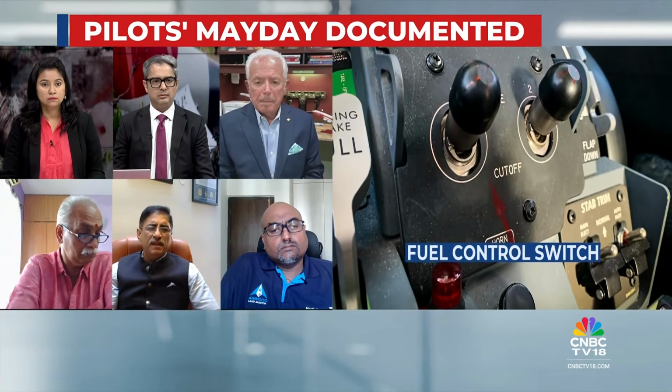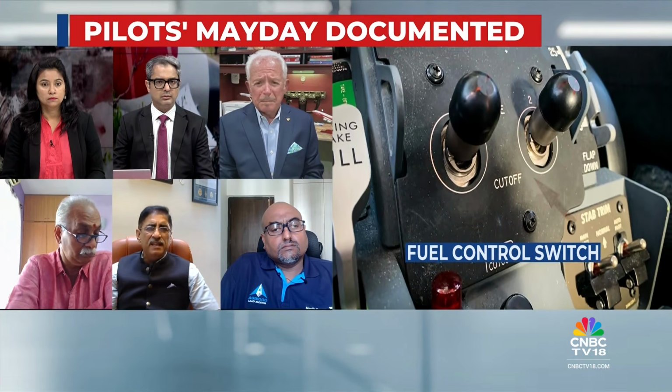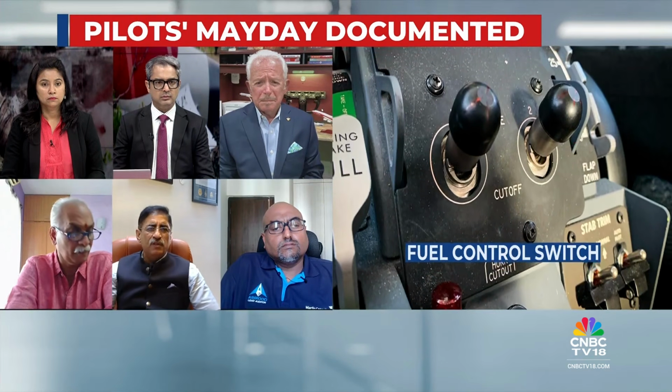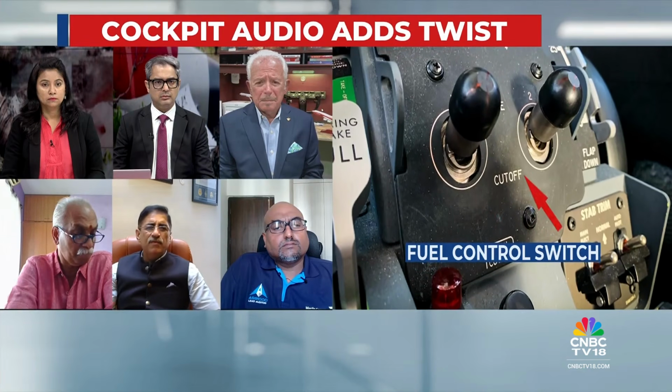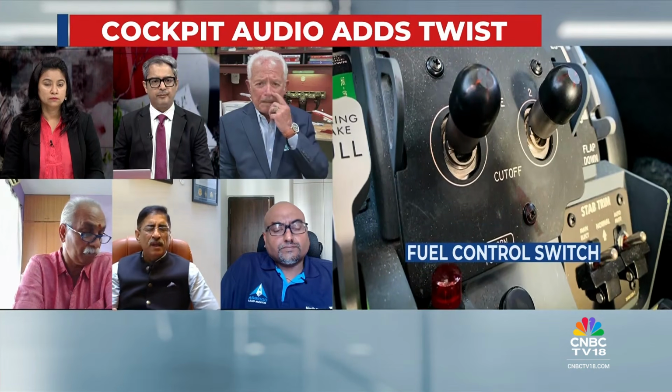Now, coming specifically to this accident, in my appreciation, it is not possible that before takeoff or during any condition, the fuel valves would have been shut, because the aircraft would not be generating that kind of thrust and power for it to get airborne. Now, it is a hot afternoon, 1:30 or 2 local time. Tarmac temperatures must be around 45 plus degrees centigrade.